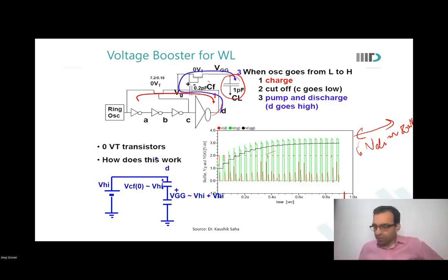Memory output will be latched somewhere, either in the next stage of flip-flop, somewhere it would be latched. At the system level also, you will need to latch memory output somewhere. Yes, sir. So you do that after access time. Then there is no problem of whether there was junk before the access time or not. Is it clear? Controller has to work like, when CS comes, only then take the output.